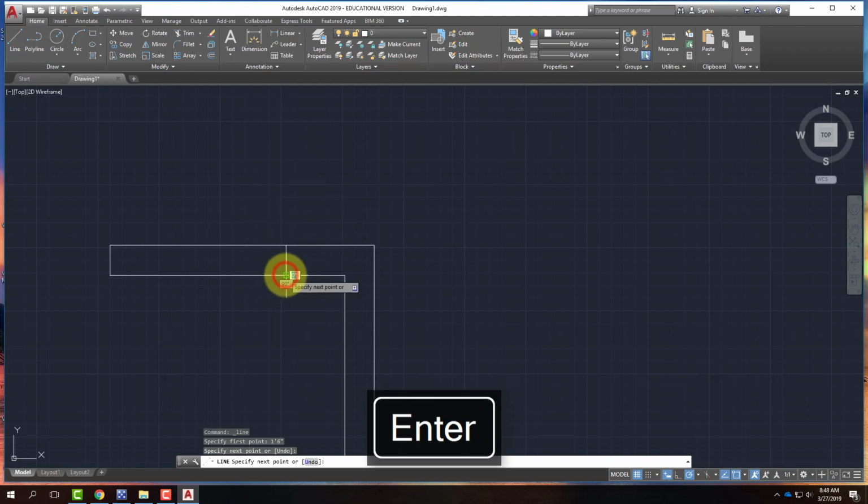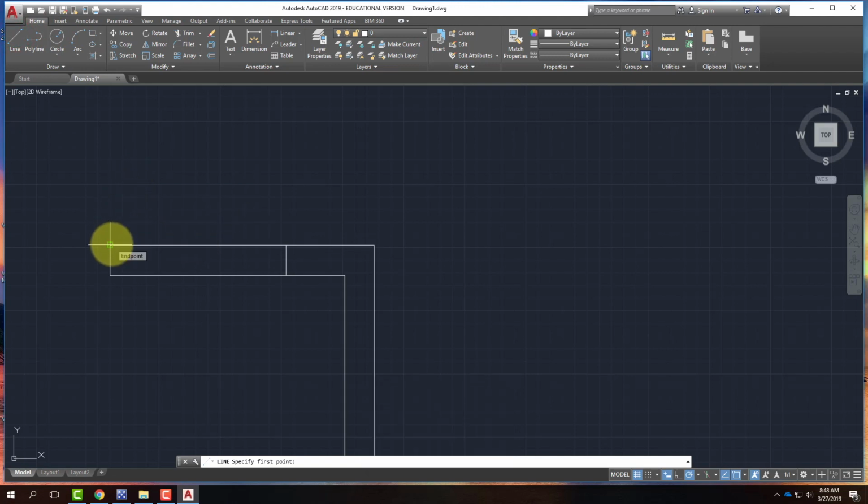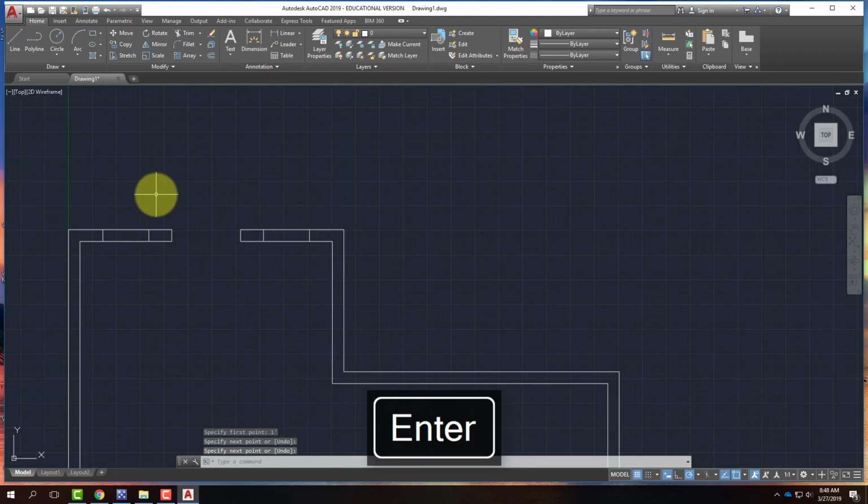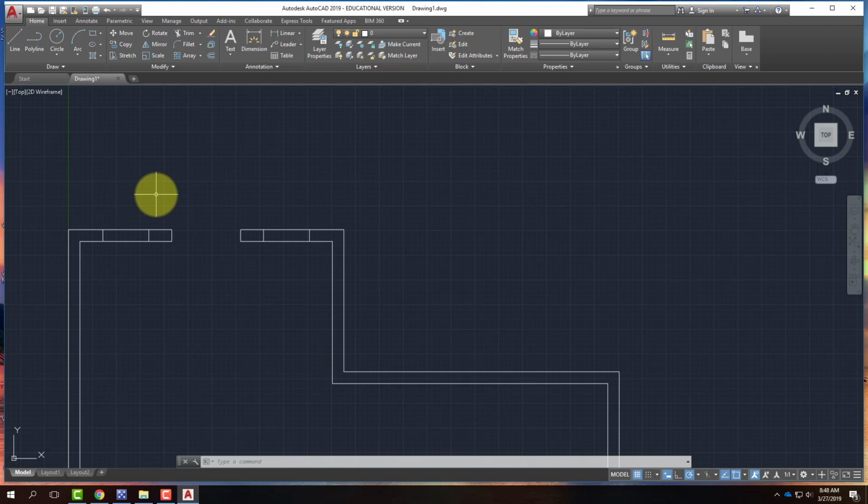And then I'll draw the line that goes down. I'll go back to my line tool. I'll move my mouse over that corner. I'll move my mouse to the right this time and type in 1 foot. And I'll draw that line there as well. So this is something that's important for you guys to get practice doing today. And if you're struggling to make it work, I'll come and I'll sit with you and we'll make sure that you have a good understanding of how this works, because it will help your drawing flow quite a bit.